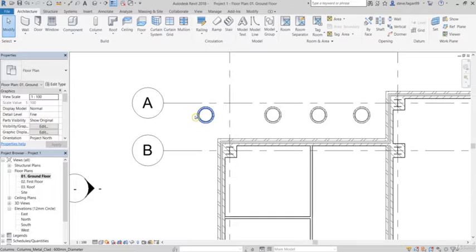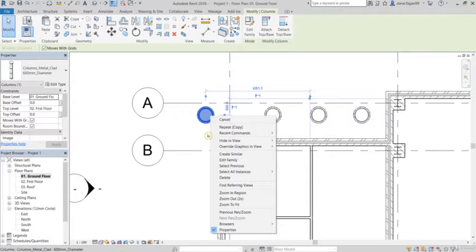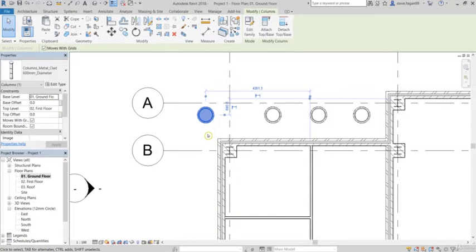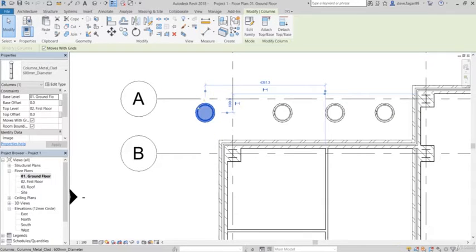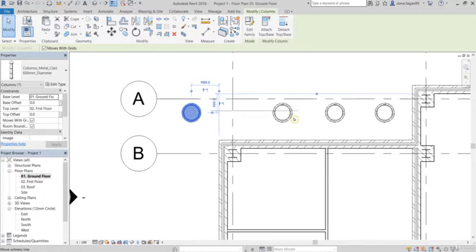Now that I have the 4 placed, what I'm going to do is adjust the position of the last column. And as you'll see in the PDF, it's a meter away from each face. So this temporary dimension here is latching on here. So what I'll do is click the blue grip, click and drag until I get the blue line on the external face and let go. And there it is, 1000. And it should automatically be 1000 from here as well.